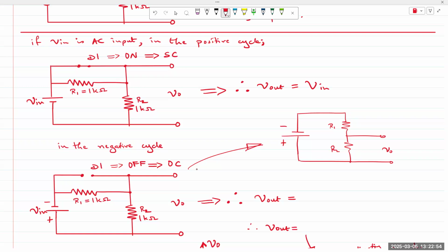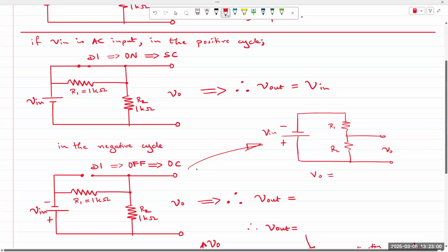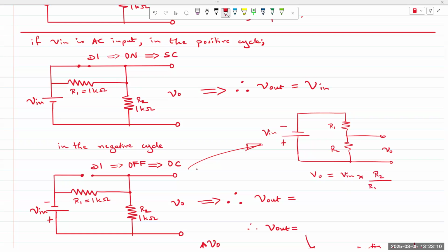Voltage gets divided, and the division results in a fraction of the output voltage. So V out is a fraction of V in, and the fraction is given by that resistor divided by the sum of all the resistors in that series connection. So R2 over R1 plus R2.